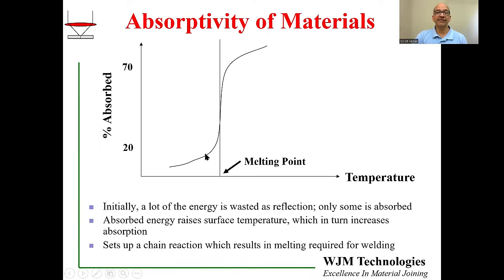As long as we have enough number of photons hitting the surface, enough energy density on the surface, we can actually melt practically any metal because of this chain reaction process. So this is a very important phenomenon that makes laser welding possible.